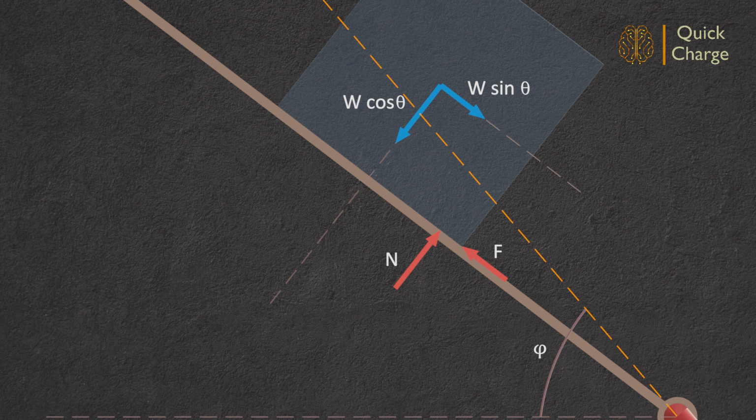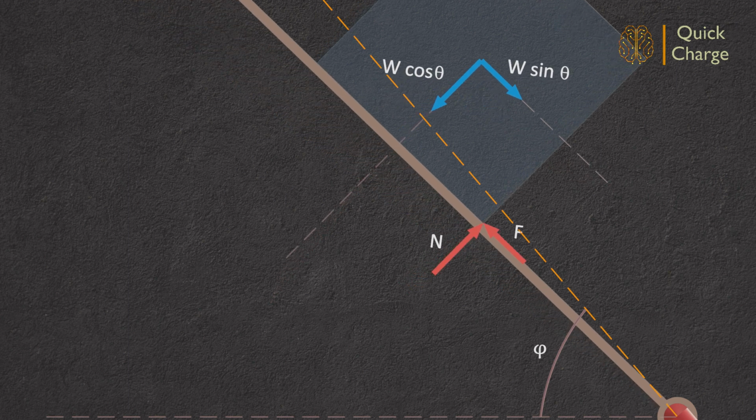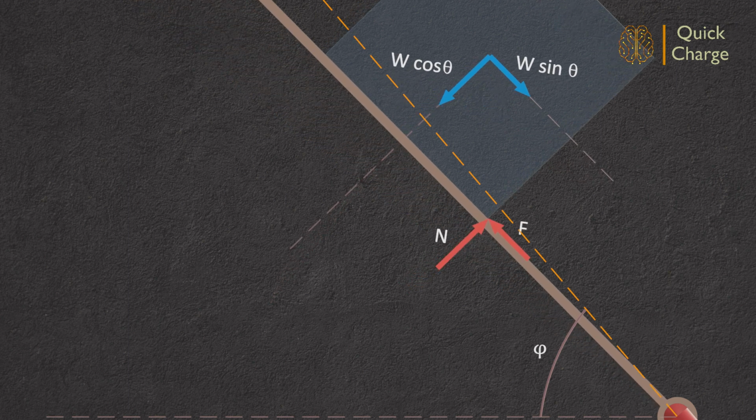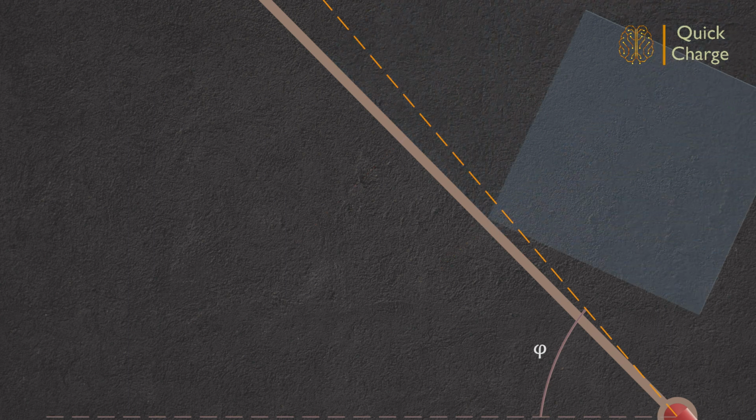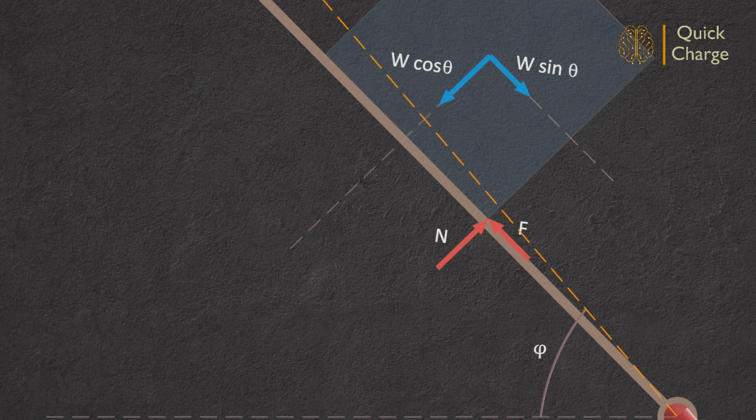As seen in case 2, the process continues until the frictional reaction reaches the limiting value. But in certain conditions like this, the normal reaction reaches the extreme edge of the object before the limiting static friction is achieved. Beyond this, the restoring moment does not increase. However, as the limiting static friction is not reached, the overturning moment increases with further tilt. This results in tipping of the object. So, tipping is happening at a lower angle as compared to sliding.